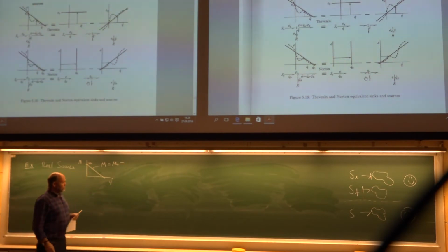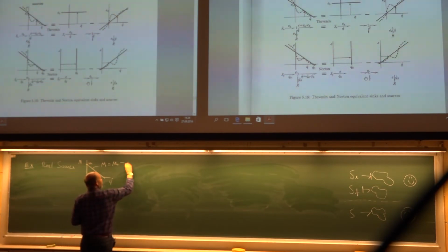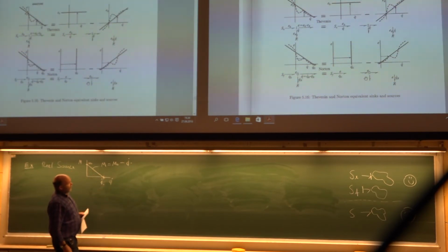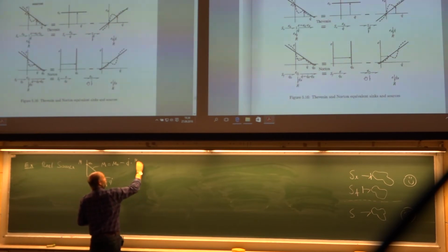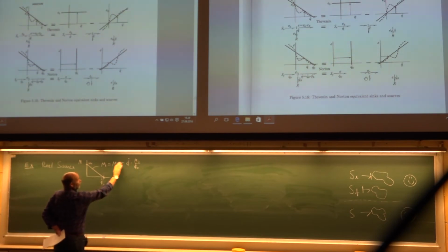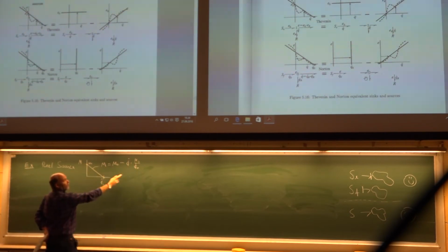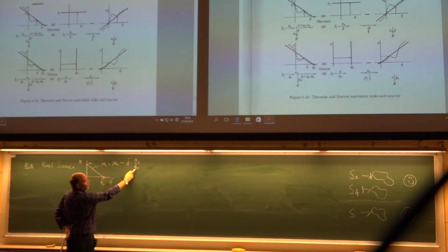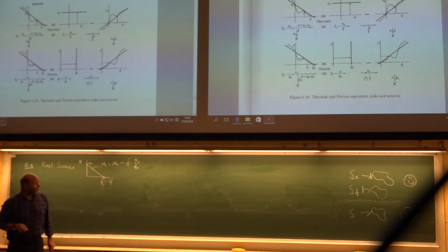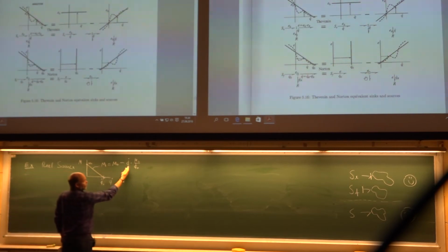And then minus phi dot multiplied with, say this value here is phi dot 0, then we have to multiply with M0 divided by phi dot 0. So that one should be correct. If phi dot is 0, the torque is M0. If phi dot equals phi dot 0, you will have 0 torque. So there you have a linear connection, M as a function of rotational speed.